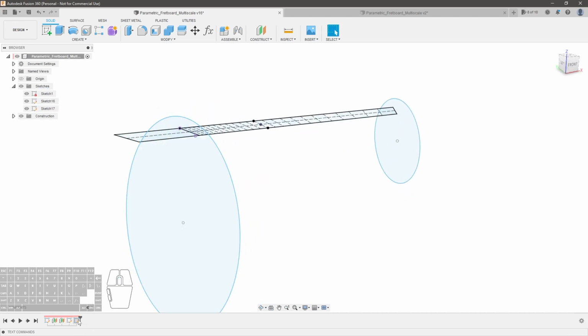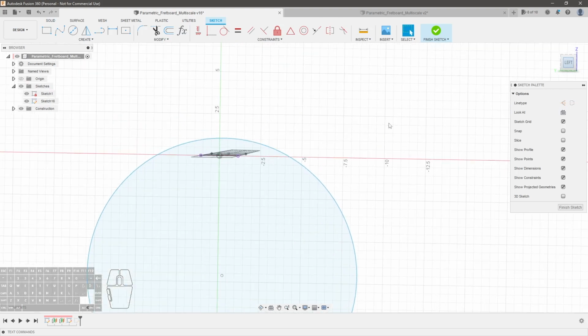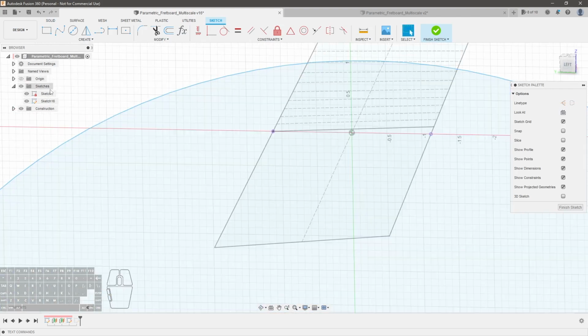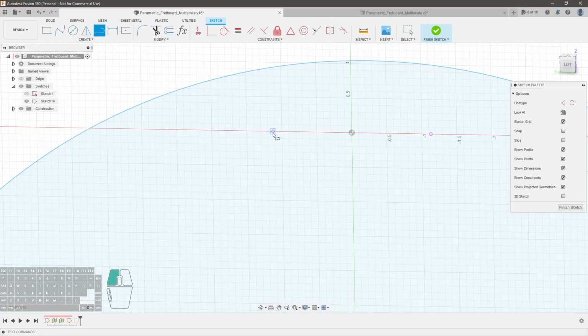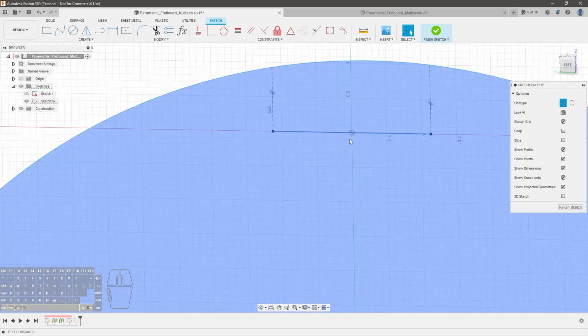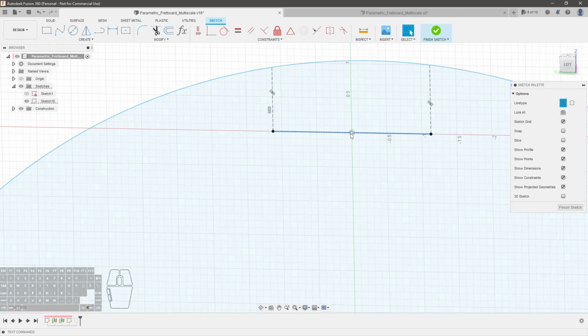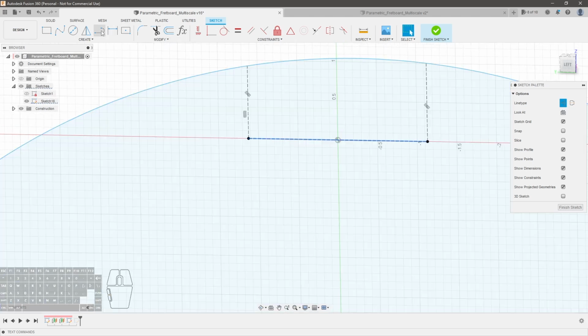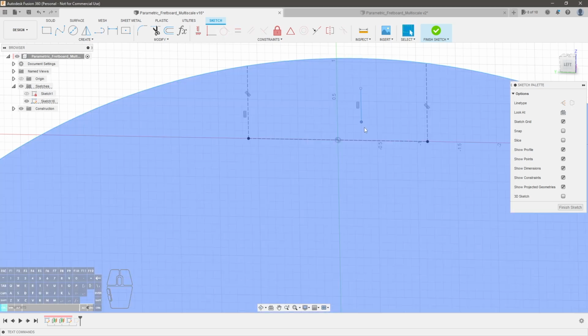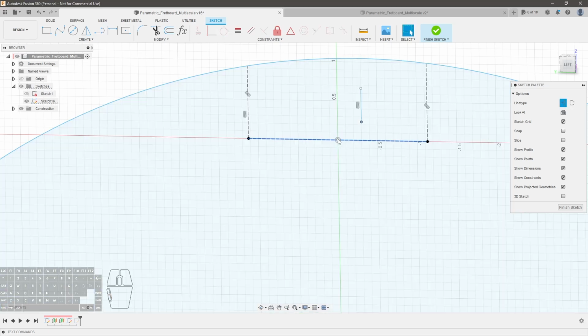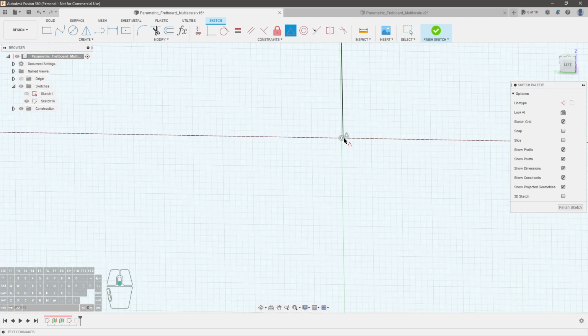So what we're going to do is we're going to go back to that first sketch. And we're going to hide the first one and then drag a line up on each one of these points. Like that, we're going to make these construction lines. And we're going to drag a line between them. Now the center point of this and the center point and this right here may not be actually the same point, because the fretboard gets angled and gets wider and tapered near the heel. And so it's actually useful to just draw a center line like this and make it midpoint to this line rather than making it coincident to this point. And it might be obvious if I show you in a second.